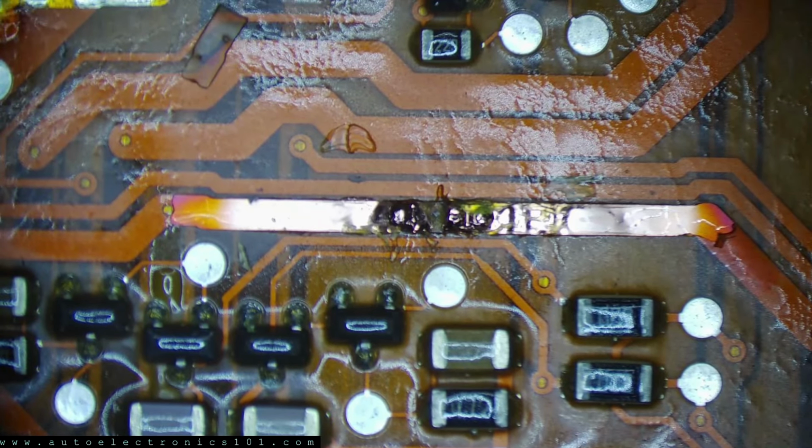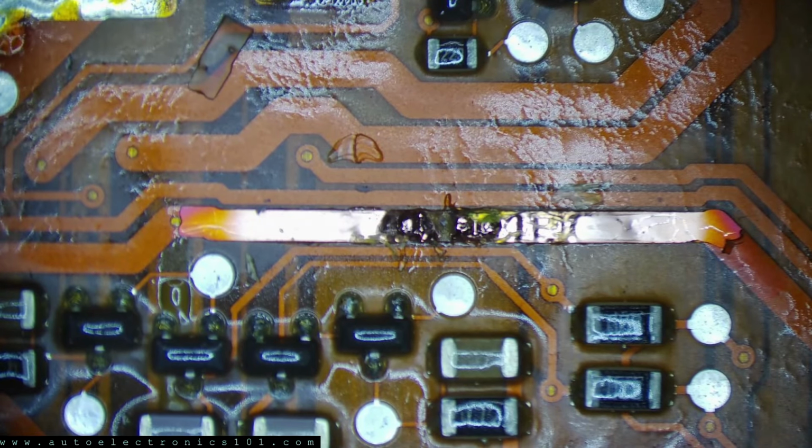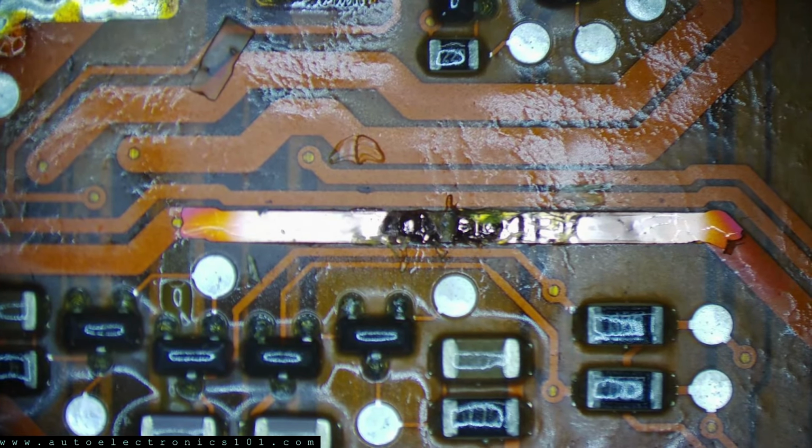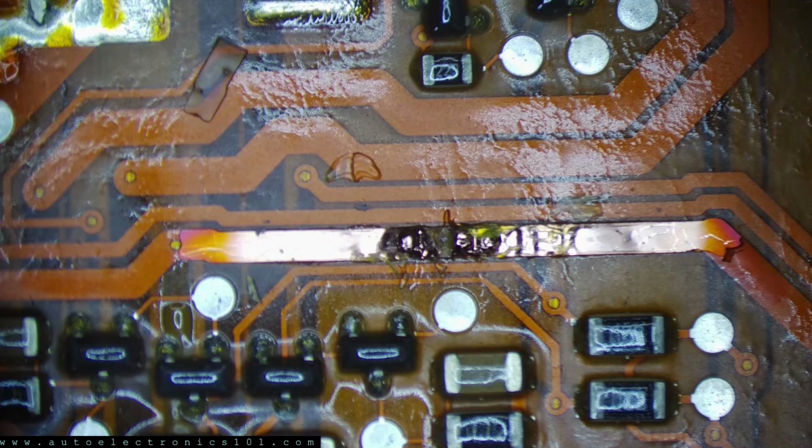All we have to do is fix this connection here. I'm just going to use a basic jumper wire, flux it and solder it on. And then I'm also, just as a courtesy, going to do my other normal stuff I talked about, which includes all the capacitors. I'll change them. And I'm going to check the tantalum capacitors.